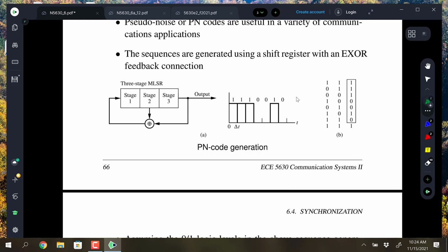Yeah, it's a repeating pattern, just like an M sequence is, but what's special about the Gold codes is, and they're used in the GPS satellites, they're used for coarse acquisition. The Gold codes, like in GPS, you have a 1023-bit long pattern, and it's the 1023-bit long Gold code. You can create a number of Gold codes that all have the same low cross-correlation properties.